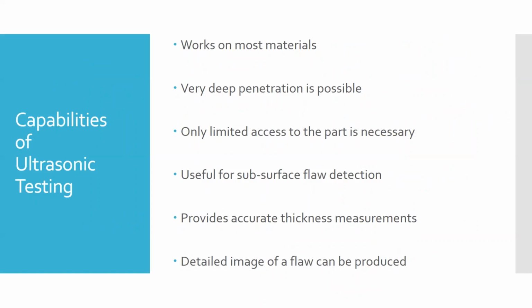And if you get cracks in any part of that pipe, you can judge about where they are. You're talking, it can go several miles underground in that case. So you don't need access to the entire area that you're looking at. I mentioned the subsurface flaw part of it. We can use it to do things like thickness measurement. And your newer testers can actually do 3D visualization, just like we saw with the real high-end eddy current testers that can do what's called a D-scan. You can do D-scan ultrasonic testing as well that can give you 3D representations of the object that you're inspecting.